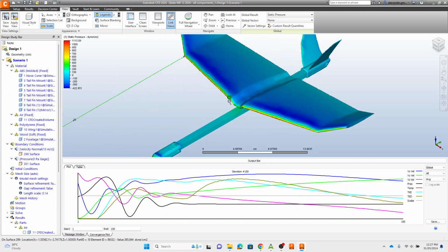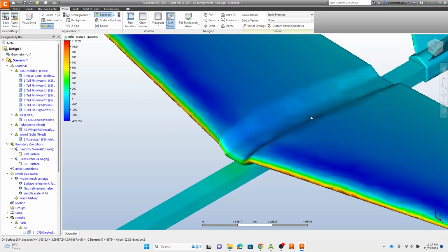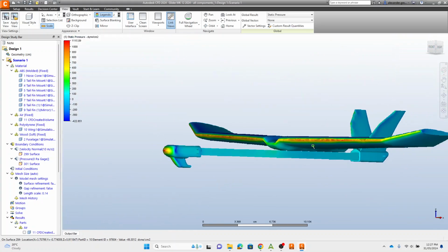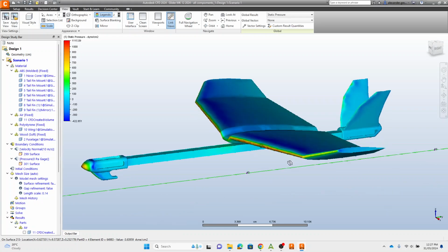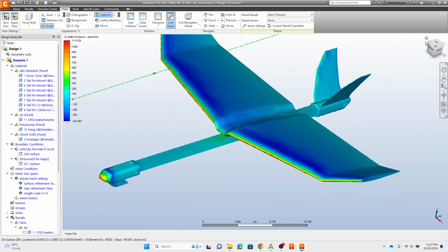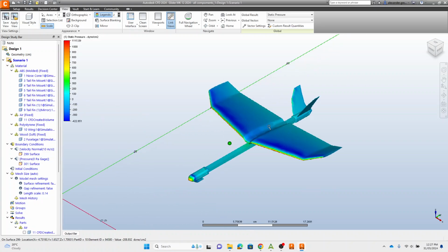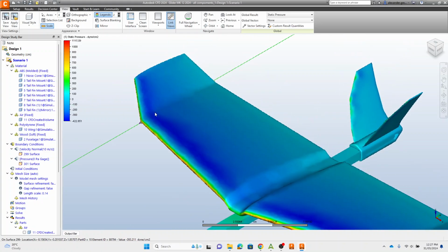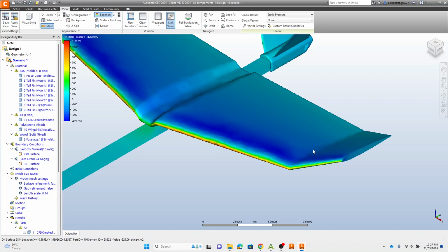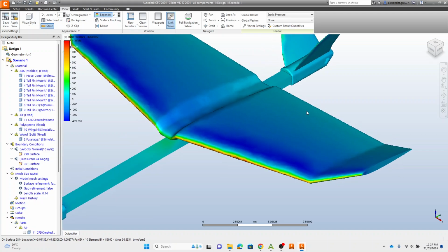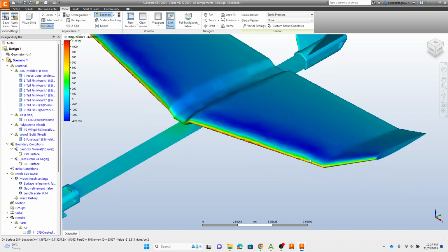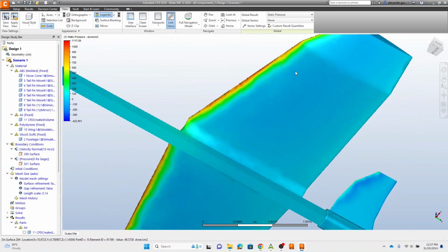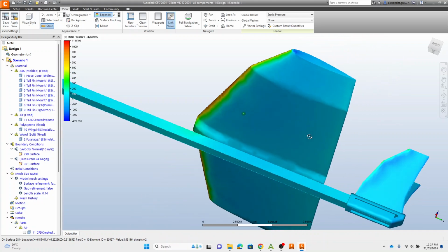And you can see here the global pressure map that we turned on as we were calculating is all done here. So that's our first indicator to how our glider is working. So if we're going off Bernoulli's principle, we can see here this is static pressure in dynes, and on top of our wing here we can see that band of low pressure, then equalizing as it gets towards the back of the wing, and then underneath we can also see a band of higher pressure as well.